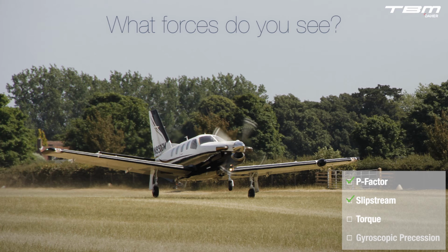With a high power setting and low airspeed, the rolling tendency caused by torque is at a maximum. It is easy to see the wingtip clearance, or look even closer at the difference in the strut compressions. See the rotation of the fuselage. The wide stance of the TBM's main landing gear provides stability against torque during the takeoff roll. Since the pitch attitude is set and not in a pitch transition, gyroscopic precession is at a minimum.